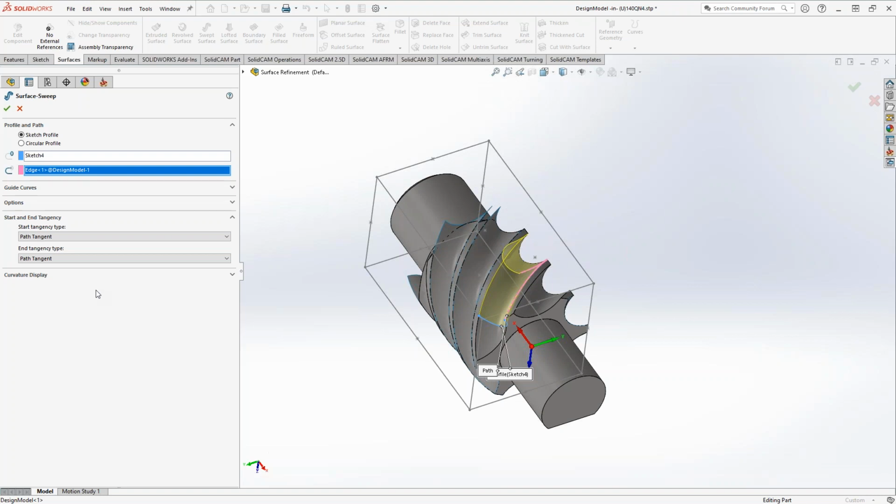There are some times where I do this with a 5-axis toolpath. I will create a cleaner surface to help with the 5-axis toolpath. If you're trying to do anything with surfaces and it's a translated part, sometimes those translated surfaces are not good. Sometimes they don't translate well. There's a lot of noise there. And because of the way the surface-based toolpaths operate, they will pick up on that, and you'll get toolpaths that go in crazy directions. If you're defining the angle of your tool by anything to do with the surface normal, then sometimes that toolpath gets disrupted because the surface normal changes in completely different directions point to point because of that noisy, badly translated surface.